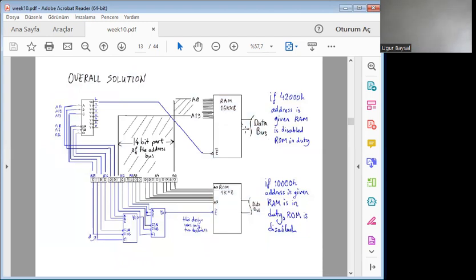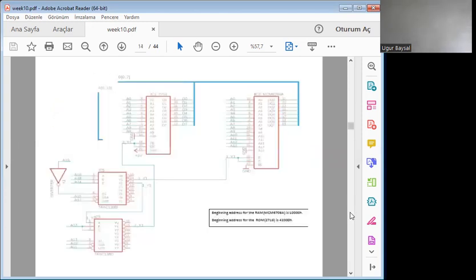Of course, the data bus can be directly connected because some RAMs or ROMs have output enable or internal latches. If any RAM or ROM has a 3-state internal latch, you can connect their outputs directly. But if not, you have to have external latches or bus transceivers. If this is a RAM, two-way data transfer could be possible by another extra control. But usually an output enable pin exists for these RAMs, so that the data bus connection is in 3-state condition.